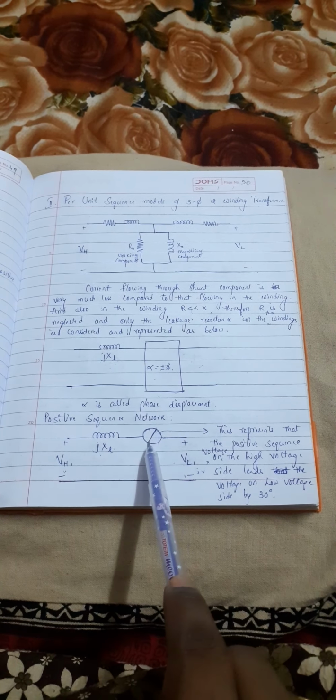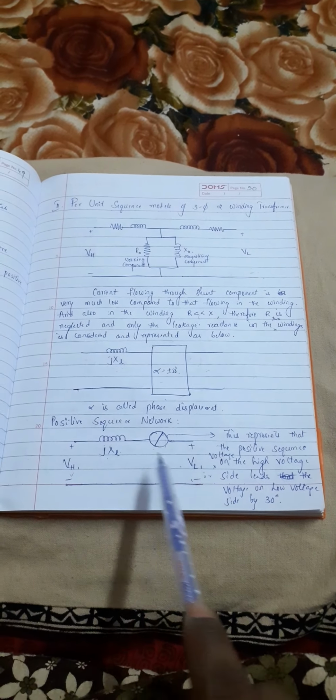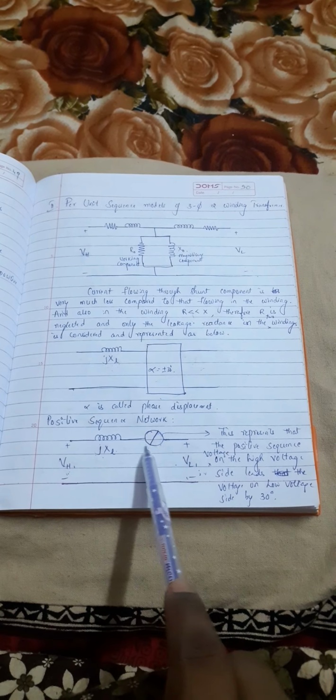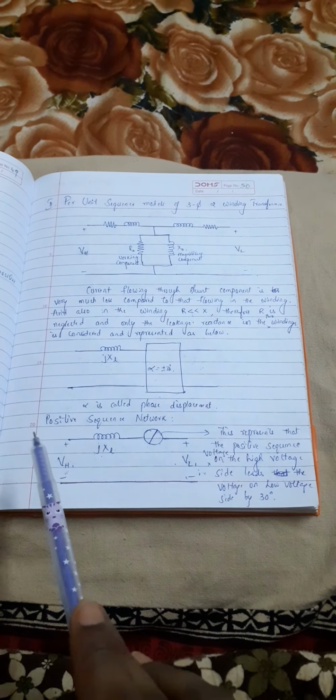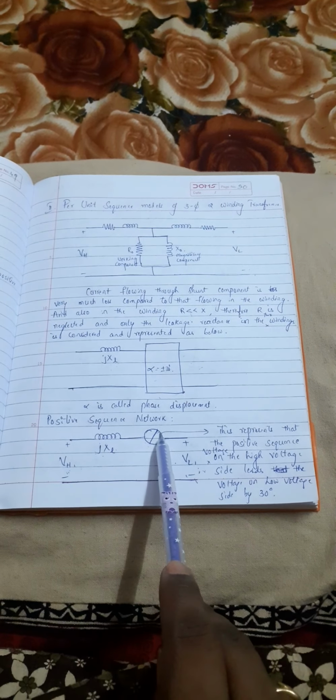Sorry, I said earlier as lagging, but it is leading, as I have mentioned here. The high voltage leads the low voltage by 30 degrees.